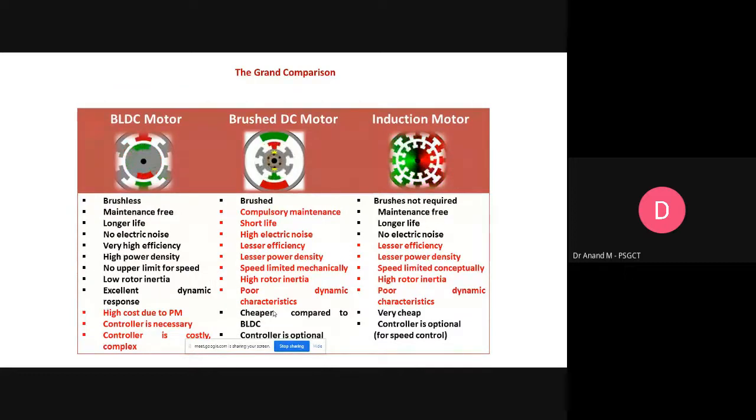That is, the torque yielded by a BLDC motor, what we call a PMSM, as the name indicates, is with respect to the electromagnetic EMF that we produce. If it is a sinusoidal EMF in the air gap, we say it is a PMSM. If it is trapezoidal, we say it is a BLDC. So the excellent power density, the torque density, and the compact size and volume make the OEMs shift to the magnetic-based drive systems instead of conventional asynchronous drive systems.